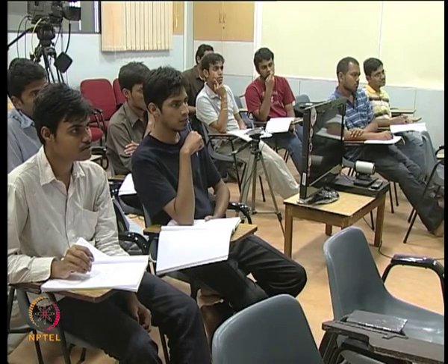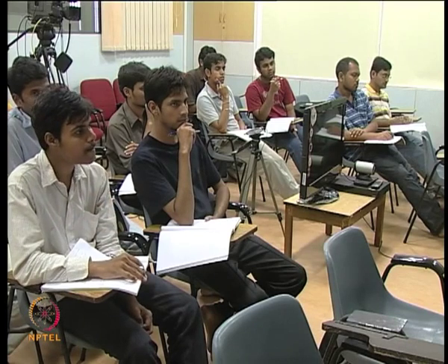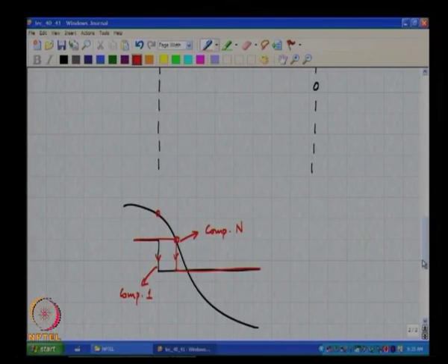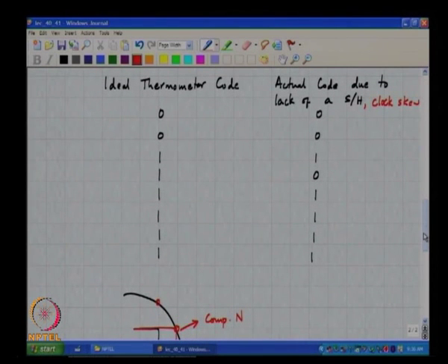Pardon? Less than one clock cycle, the skew will be the same, right? The skew is definitely, at least you are hoping, much smaller than a clock cycle. Because the signal is held constant over that period. That is all. The problem as you can see is that the signal is changing within this interval. If you make it stay constant, the fact that you have clock skew does not really matter. Of course, you have reduced the amount of time to make a decision, but the slope is 0, therefore all the comparators are seeing the same input. So, having a sample and hold helps significantly in that way.